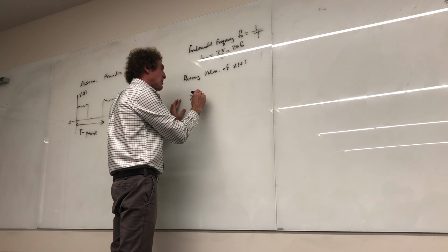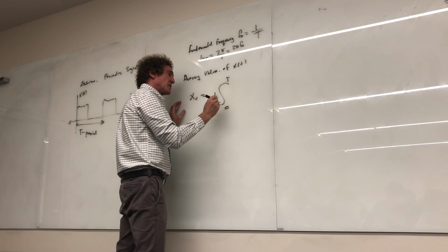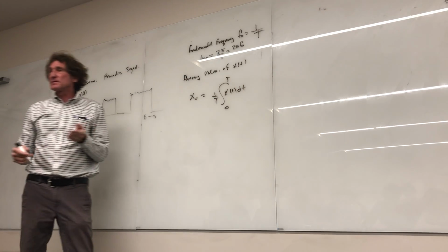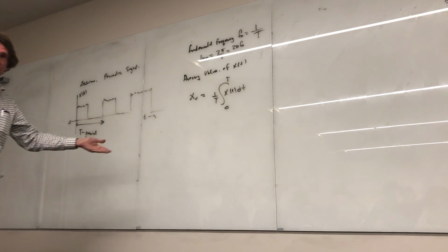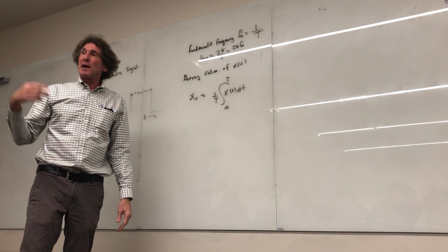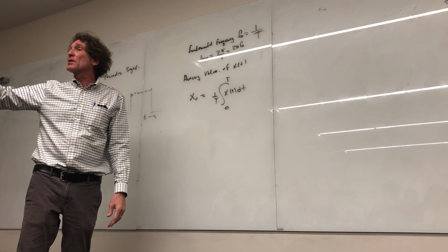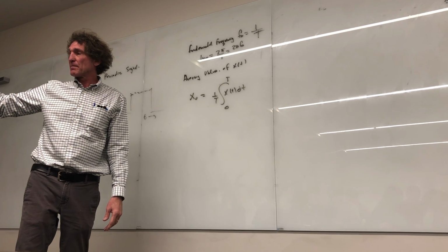The average value is always the integral from 0 to T times 1 over T of the signal x of t dt. That's all it is. So the average value of anything is just really integrating that function over a period and dividing it by the length of the period. You're probably very familiar with that concept, average value of things, right? The average power, the average, that's just common, right? Now a sine or cosine wave have an average value of 0. Remember that, and that's important to also remember.